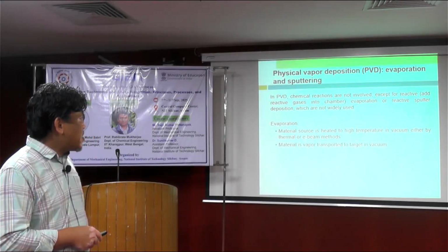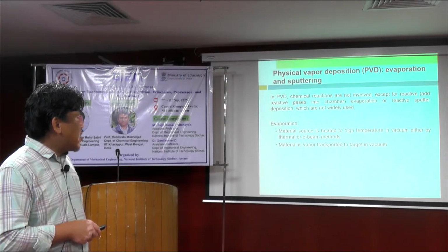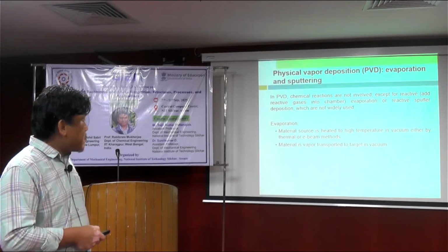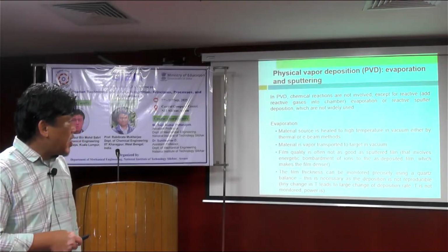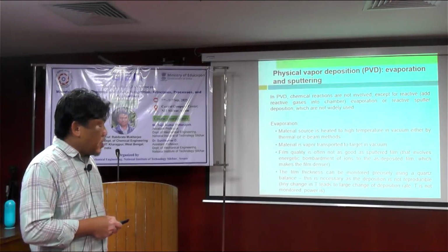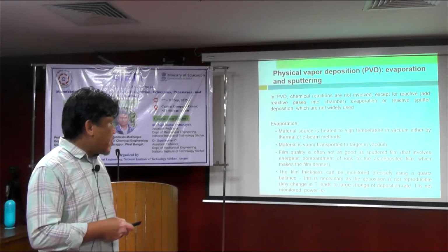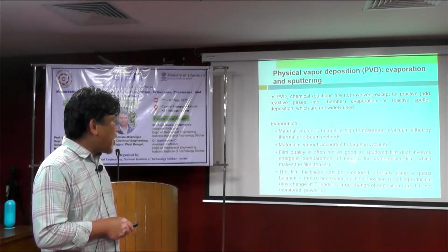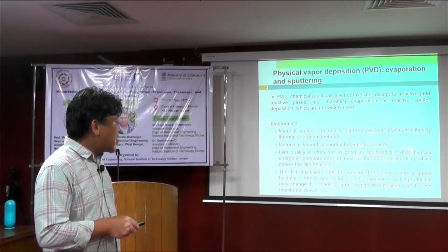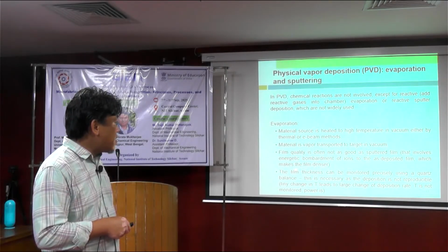The material vapor is transported to the target in vacuum. Then film quality is often not as good as sputtered film. That is the comparison we're going to do later on: sputtering involves energetic bombardment of ions on the as-deposited film, which makes the film denser. So that is a quick comparison between evaporation and sputtering.